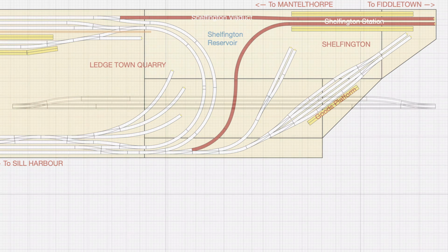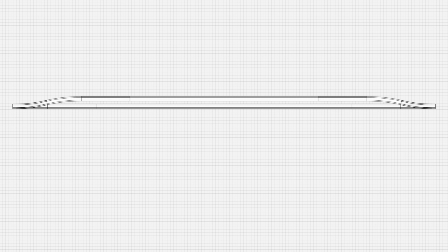The next decision to make is how big the blocks need to be. My current thinking is that each length of track between turnouts should be split into at least 3 blocks. This should allow for initial detection of the train travelling between the turnouts in the first block. The second block detection could be used to trigger braking, and the third to make sure that the train had stopped.